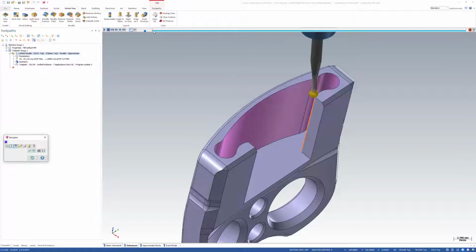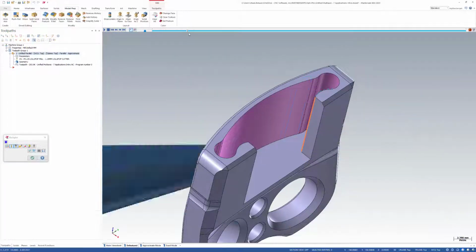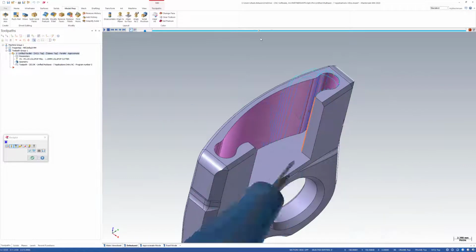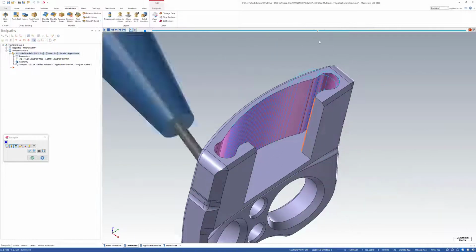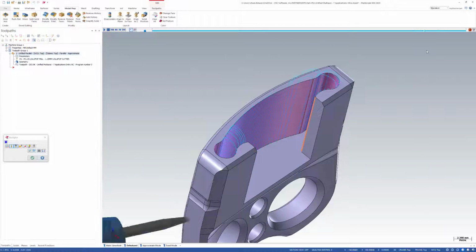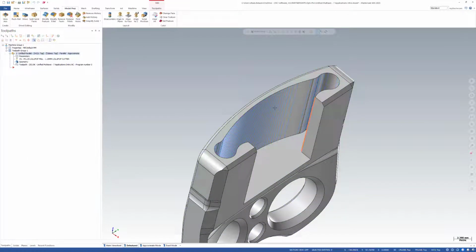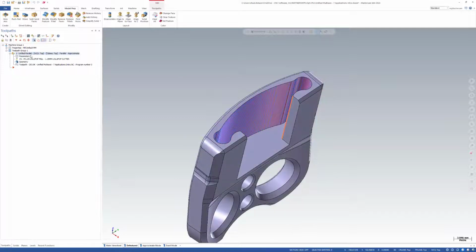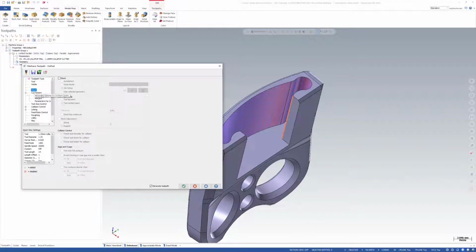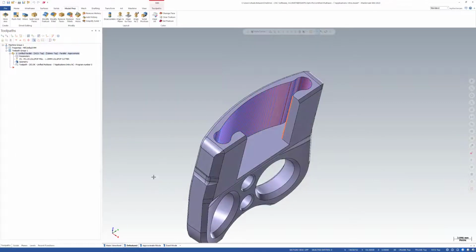When we backplot this, of course ignoring tool axis control, what is going on with the stepover, right? It's seemingly consistent in some places, inconsistent in others. Well, this is all due to how the stepovers are generated in Mastercam. So if we look on the advanced options page, if you're familiar with approximate versus exact mode, this should hopefully be a review.